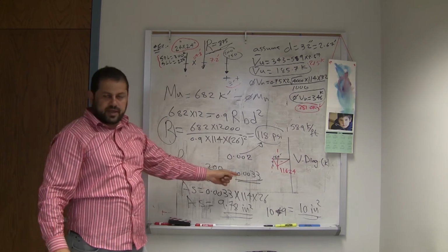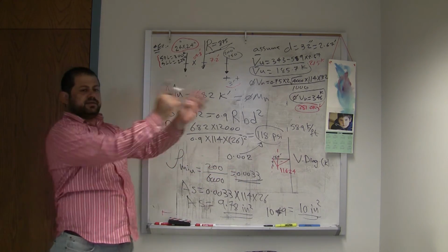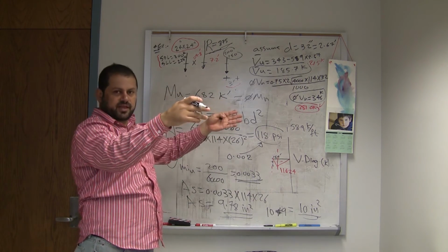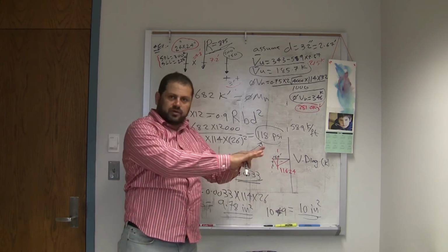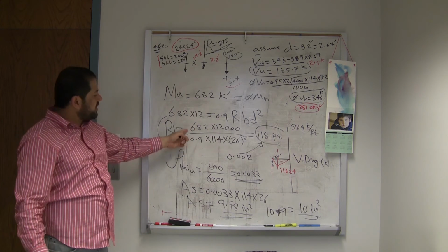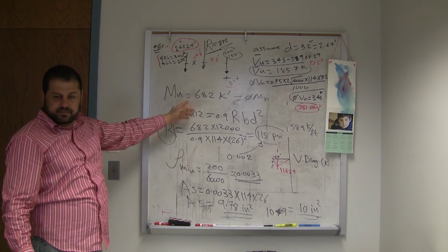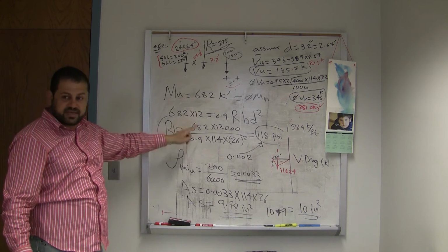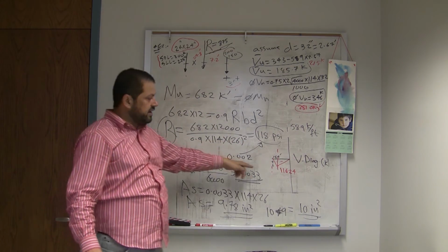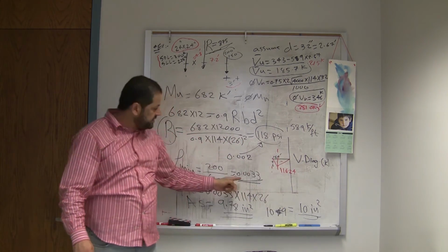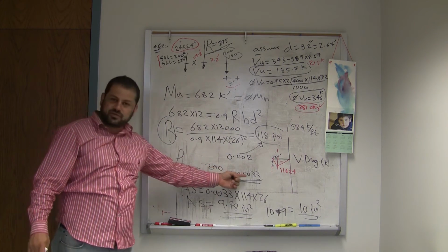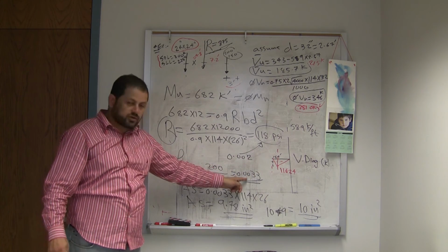You will have 10 bars over a 9.5 width. You subtract the cover from here and the cover from here, so it's almost that. But the guys will distribute those 10 at equal distance from there. You can do the design again, but if this one requires the minimum, it means everywhere is the minimum. If this 682 required less than the minimum, for the same d, the minimum will be everywhere. Remember, this is structural. Rho minimum for it is 200 over fy, or 3 square root of f'c over fy, which will be 0.00332. So this controls for the minimum.